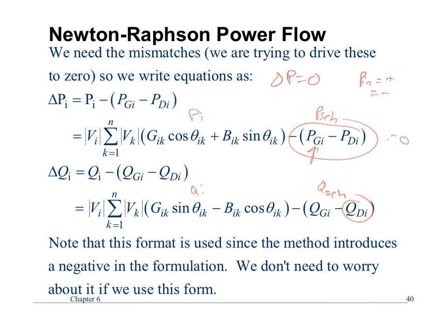So as long as you have power generated, that's power going into the bus, right? You generate power, you supply it to the system, that's a positive number. If it's demanded power, you're taking power out of the bus, okay? So if you put PG as a number and PD both as positive numbers, you don't have to worry about the signs. I've already laid that out for you. Those signs are already taken into account correctly. You just say it's PD or PG, and you're done. All right?